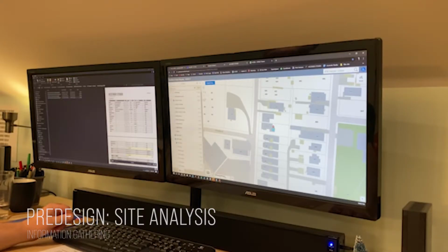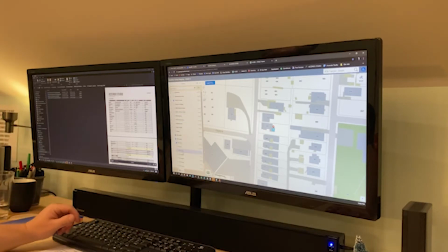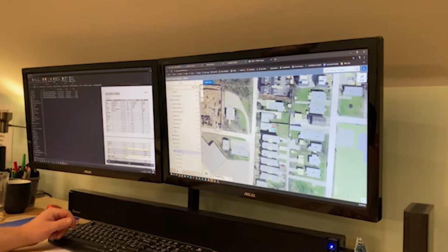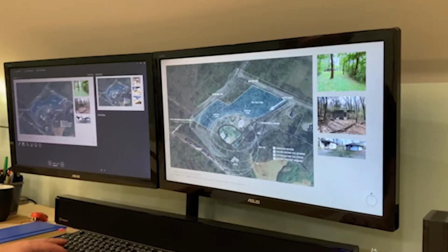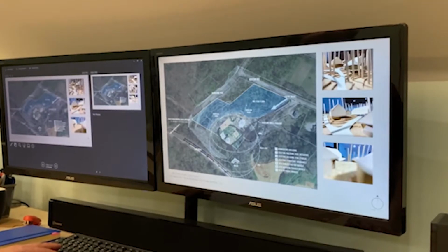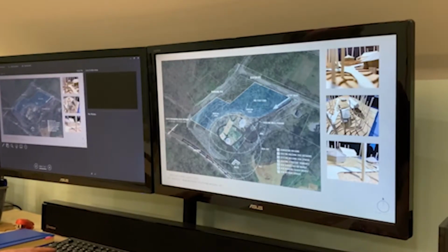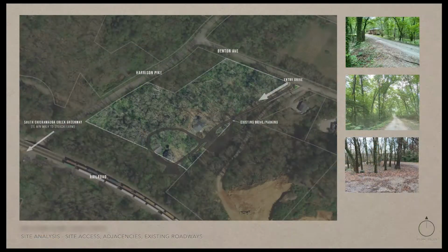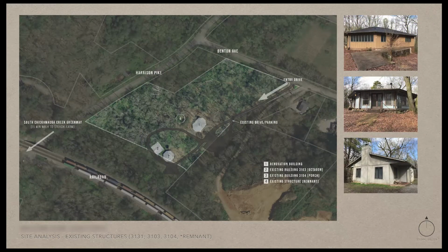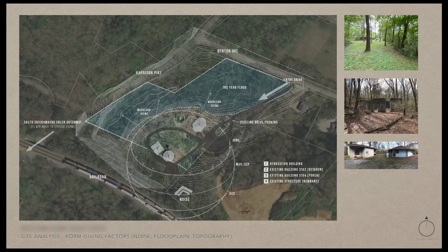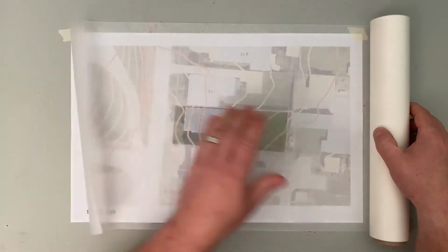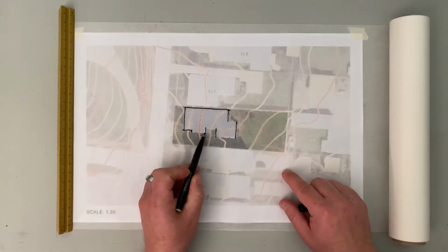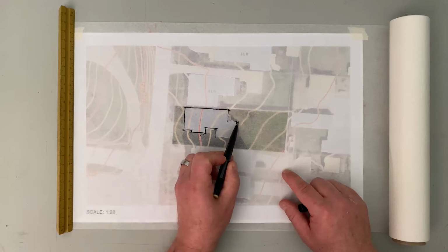The property or site is a strong generator of ideas and building forms for me, so I begin all new projects with an analysis of your site. I review the local site conditions, climate, wind patterns, solar angles, topography, and other significant features particular to your property. I overlay any local zoning restrictions, setbacks, etc. on this plan and create a site diagram. This diagram usually begins to suggest candidate building sites and opportunities which together we'll begin to explore in phase 2.